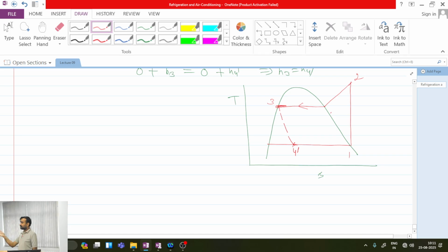And why am I representing it with a dashed line? We all know that all the reversible processes are quasi-equilibrium processes. The meaning of a quasi-equilibrium process is that in between the initial and final points, I can represent all the intermediate states. That's why I can confirm that this will be the process path. But when I have an irreversible process, I cannot know the intermediate states because the process is not quasi-static. That's why we represent it with the dashed line. Okay. Now comes another point.